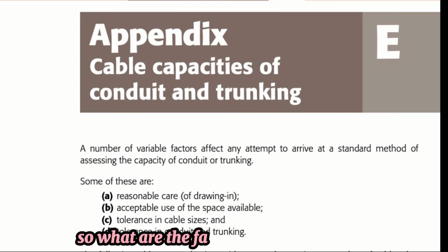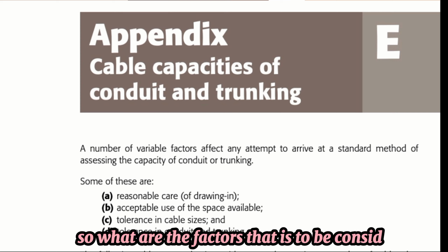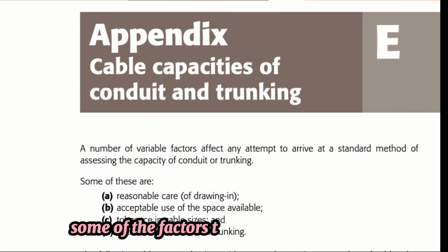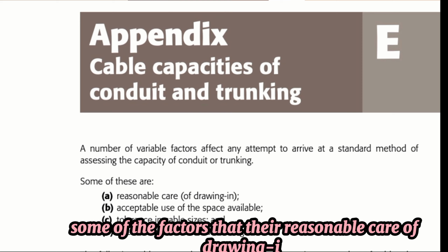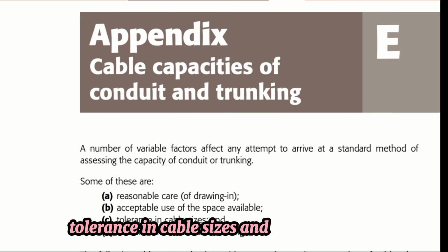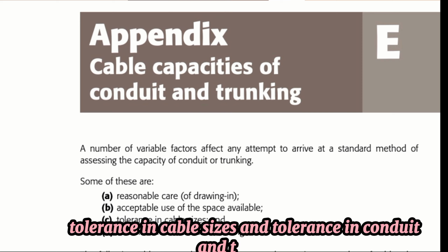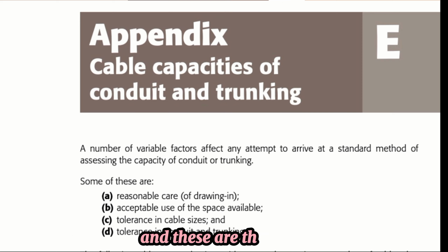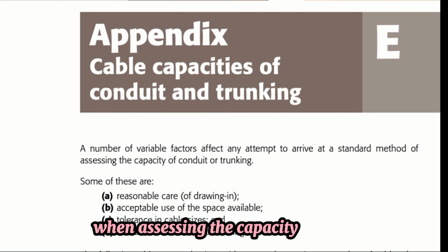So what are the factors to be considered while doing this? Some of the factors are the reasonable care of drawing, acceptable use of space available, tolerance in cable sizes, and tolerance in conduit and trunking. And these are the factors that must be considered when assessing the capacity of conduit or trunking.